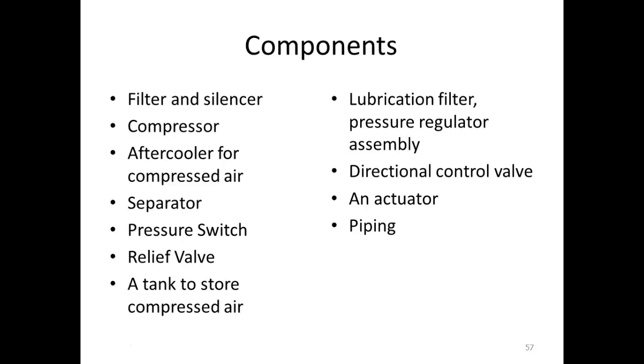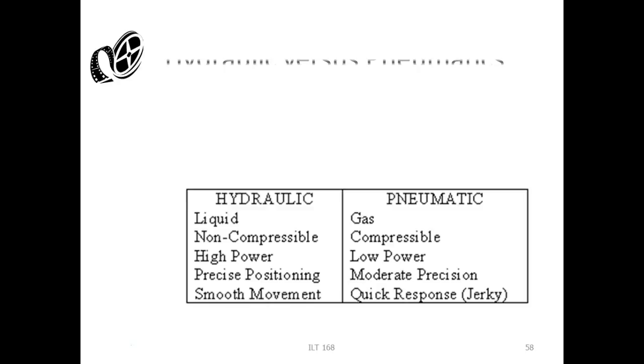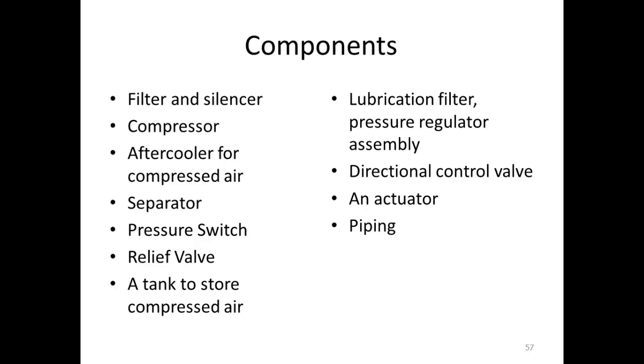In your compressor, you need it. Unfortunately, I'm one of the world's worst at not bleeding that off. You're supposed to bleed it off every time you use it. What happens if you don't? Corrosion. Well, rust. Even though they do coat the inside of the tank with an anti-corrosive material, if you leave water there long enough, it's going to get through it and start corroding it.